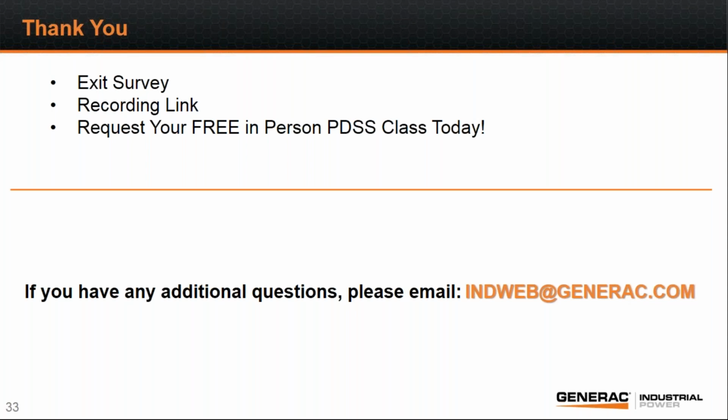How does a regenerative drive on an elevator affect the performance of the generator? Normally the performance is unaffected unless you push too much power back to the generator, at which point you're going to get an overspeed shutdown.